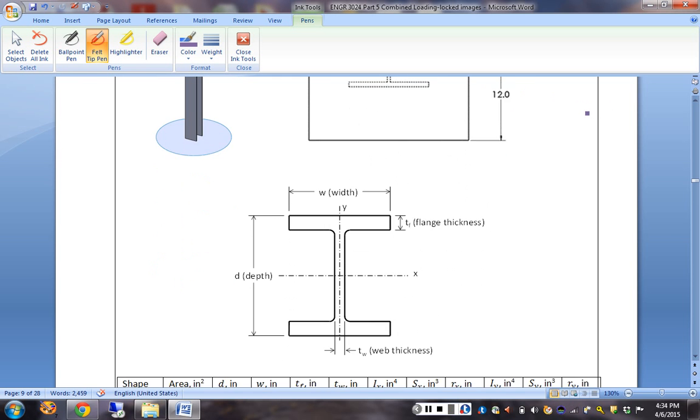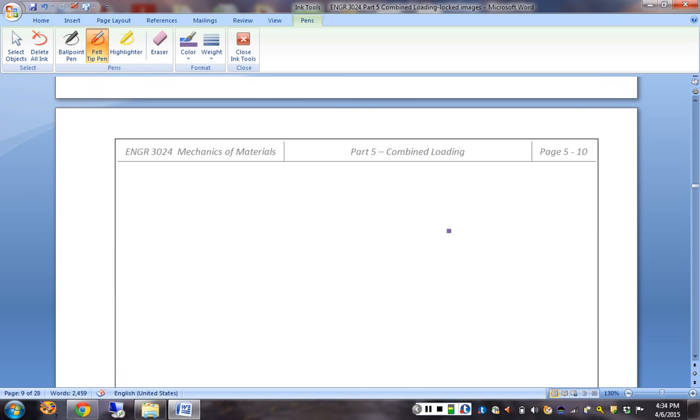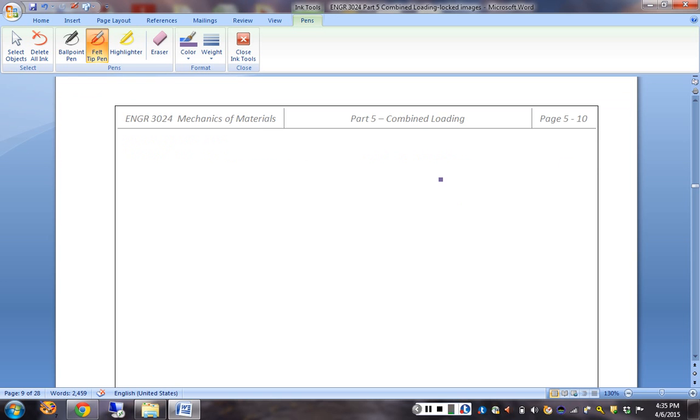So we've seen the beam tables before, where it gives various parameters. It gives distance, and it gives the moment of inertia about either one. So all of these are quantities that we're going to need. We know that this is a cantilever, so we know that the worst case scenario is going to be back at the connection point at the base. Like if we took a hacksaw and cut it off right at the concrete where it's connected, that's where our worst case will be.